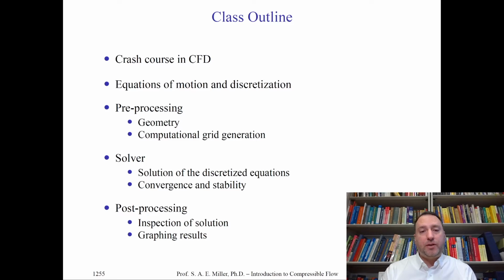The numerical error can be assessed in multiple ways. We will look for convergence, that is, as the solver runs, the error in the solution decreases and becomes very small, ideally on the same order of the machine error of the computer we're running on. We also want our solutions to be stable, meaning we do not want our solvers to blow up and say not a number, which is a common error in CFD if things are not well posed with the setup of the simulation, boundary conditions, and grid.